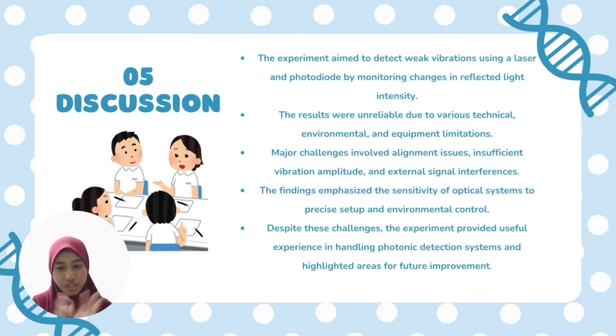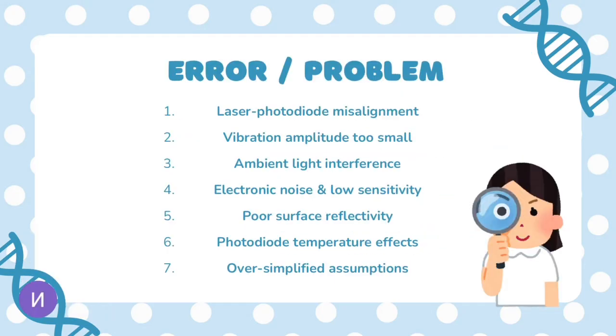Varying frequency and screen distance helps verify the relationship between vibration and the measured signal. This experiment provided us useful experience in handling delicate optical systems and highlighted areas for future improvement. Applications include vibration monitoring in bridges, towers, and buildings, seismology for detecting subtle ground and seismic activity, precision engineering to track fine mechanical movements in machinery, and biomedical settings such as non-invasive monitoring of biological vibration, for example pulse or vocal cord vibration.